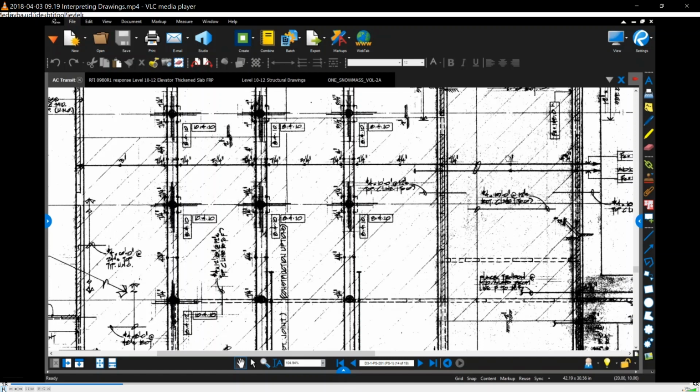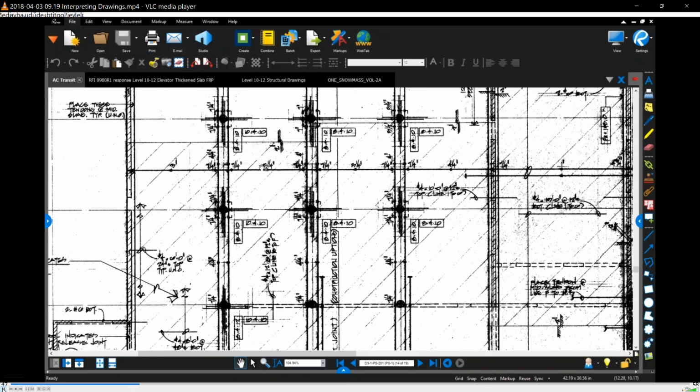This is the low point at the mid span of this slab span, and this is the profile of the tendon, measured from the soffit, or bottom, of the slab. The centroid of the tendon is 1 inch. Then at this high point, it's 7 1/4, then 4 1/4. This is a shorter span, so it doesn't need as much profile or uplift. Back up high to 7 1/4, and then down to 5 1/4 here. So you can walk through and see the profiles of these cables.